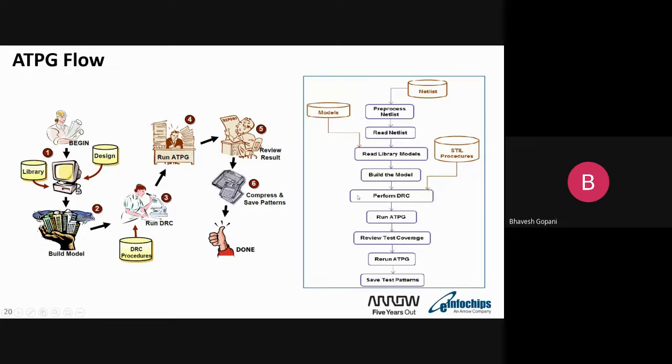Sometimes everything was clean on the insertion side, during scan insertion, but here some DRC pops up again. Those might be valid DRCs, or sometimes due to constraints we are using while reading the netlist, where we need to put some ATPG constraints in order to perform ATPG. Due to those constraints, some DRCs also occur. So we need to fix those DRCs before generating the patterns.